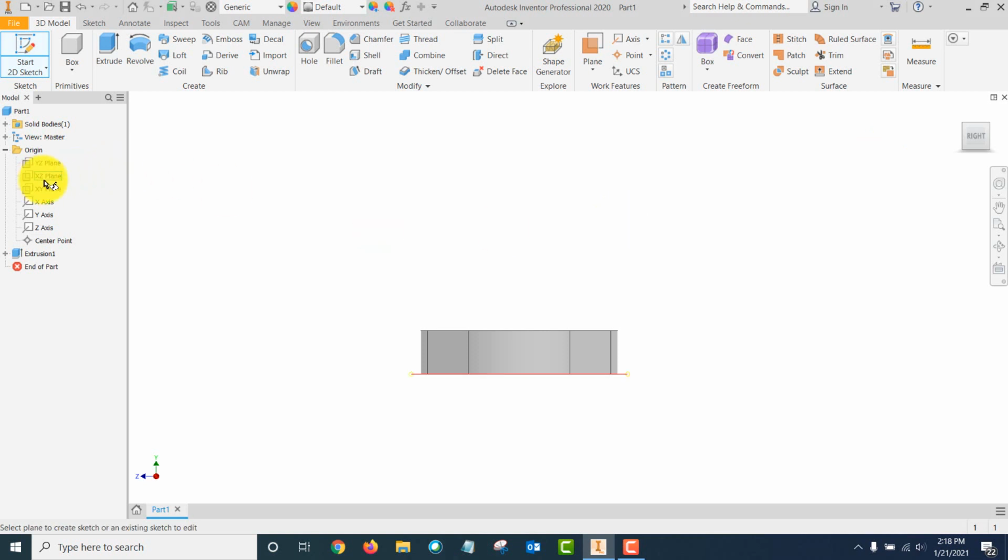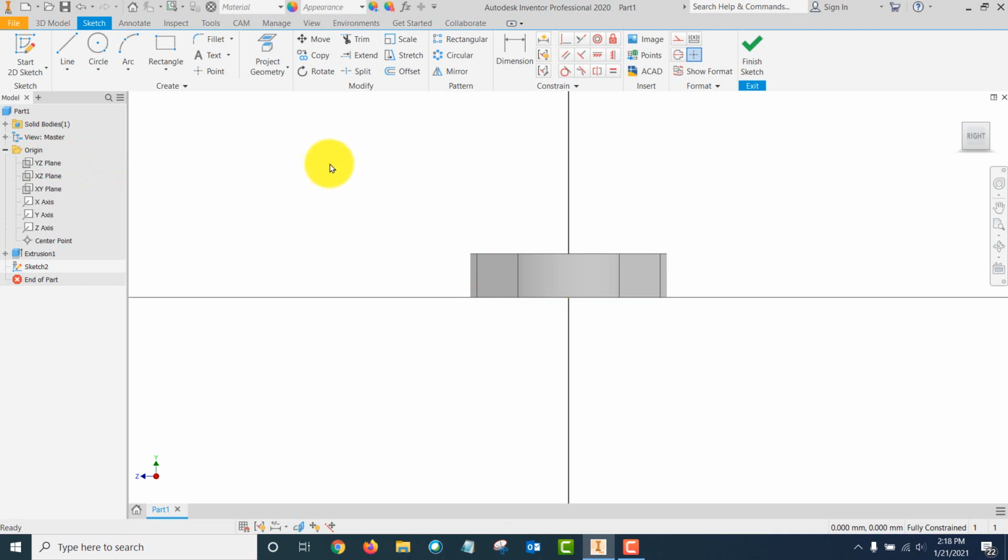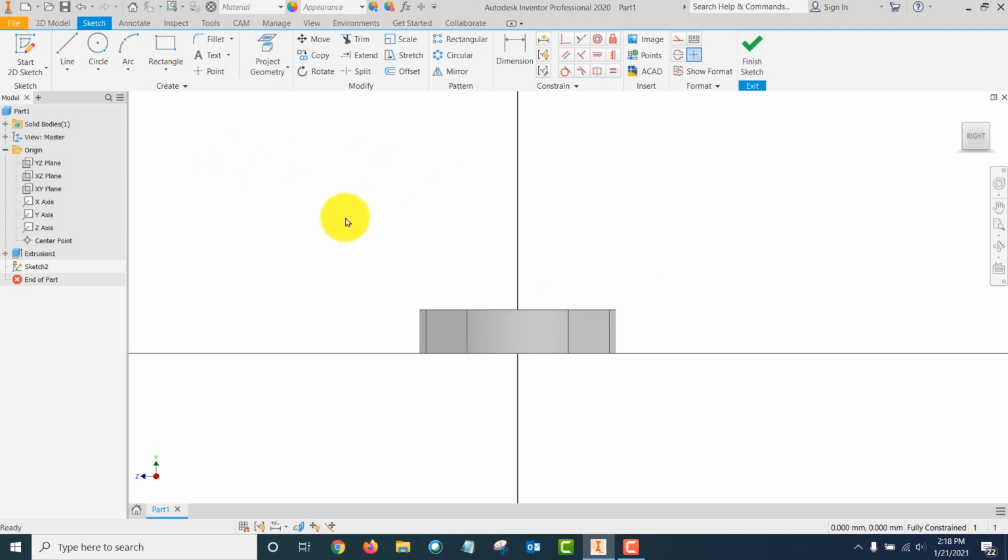It didn't pick up; I hit the cube instead of the plane I wanted. Now you can sketch, or we can slice our graphics with F7 or click that button. There are a couple of ways to do this, projecting geometry or using the constraint, but anyway, I want it centered on the axis, so I'm just going to draw it.